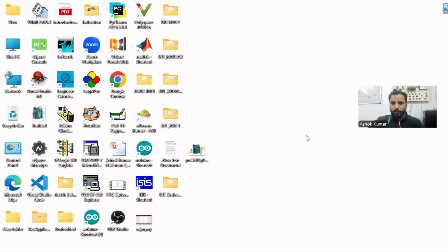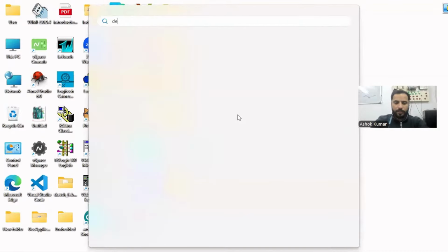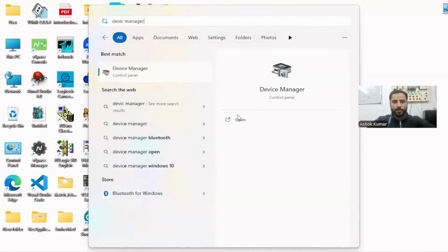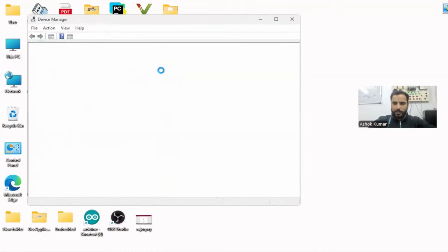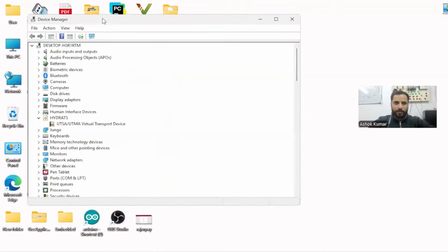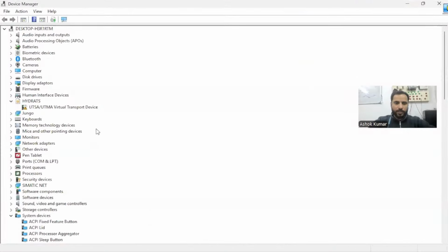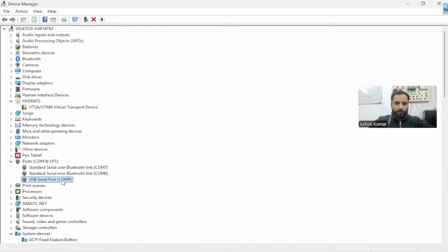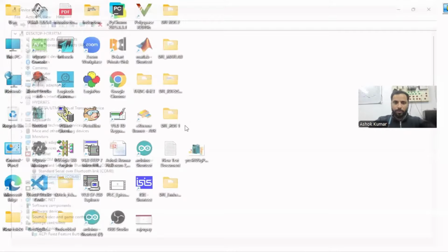So I'm going to interface this Micrologix 1400. The very first step, which I told you yesterday, is the same for today: Device Manager, where we have to check the COM ports, because now the PLC is changed, obviously the cable is changed, and obviously the port is changed. So we need to verify the port number. The port number is COM9. In this case also, I'm using RS232 standard serial communication, and the cable is an RS232 PM02 DB9 male-female USB connector, and this time it is connected with communication port number 9.